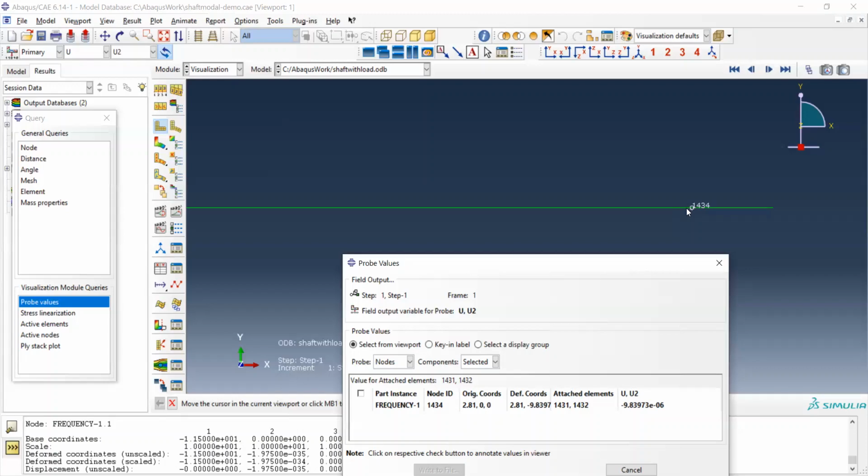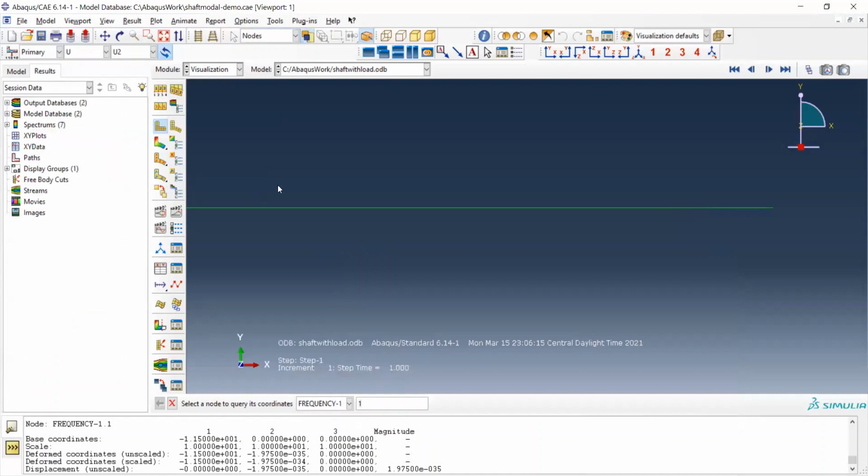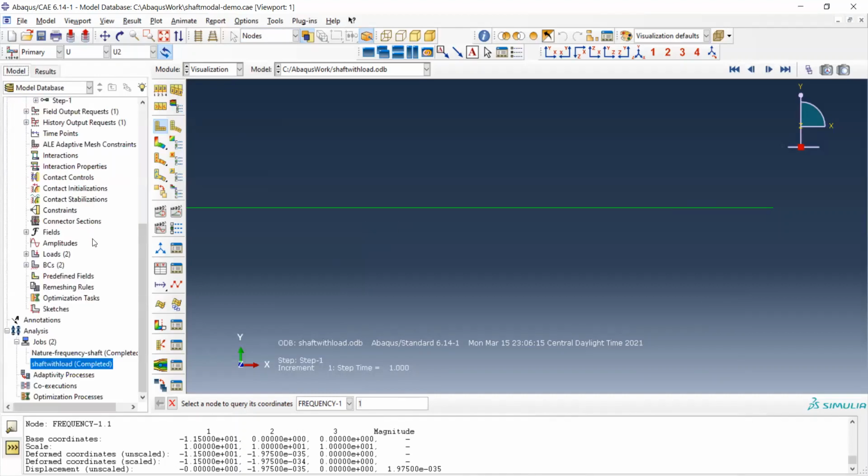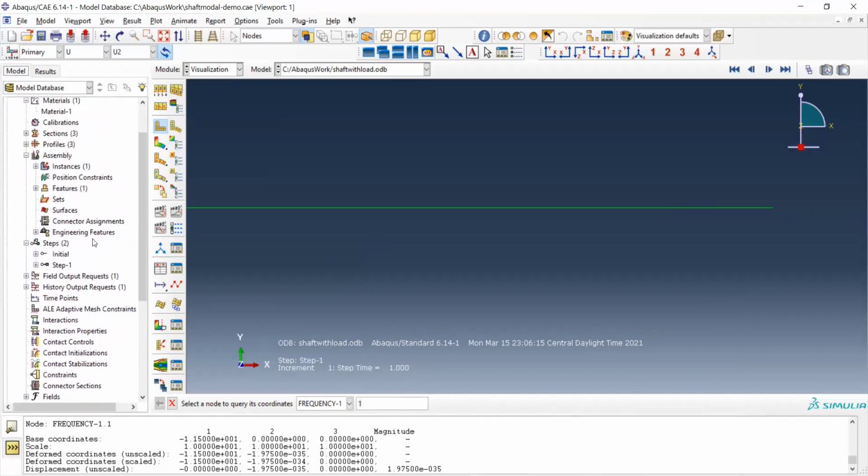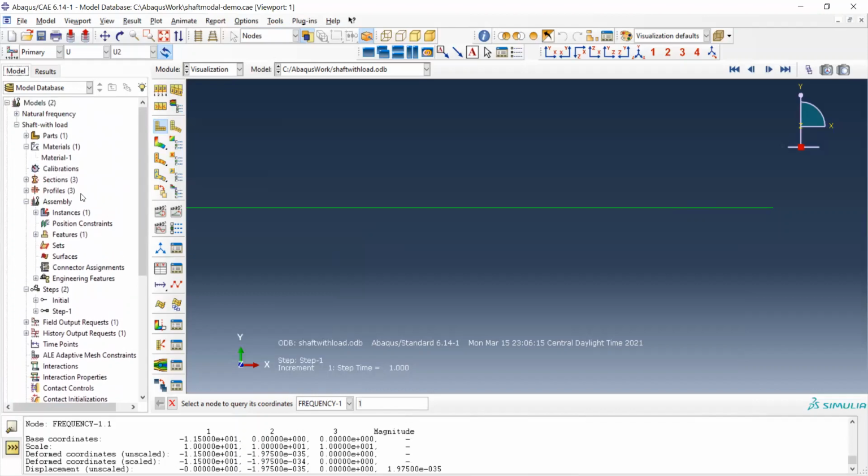So if this is the case, delta AA and delta BB should be obtained differently. Up to now, delta A and delta B are the deflections at A and B when both loads are applied at point A and point B. So this can be used for the Rayleigh method. For the Dunkerley method, what you can do is this, okay? Suppose now I want to get, let me see.